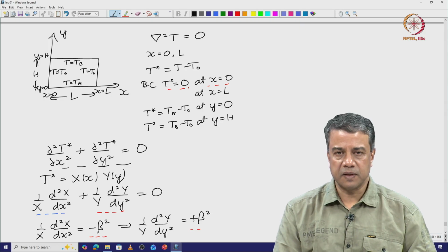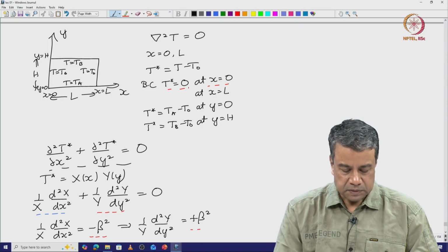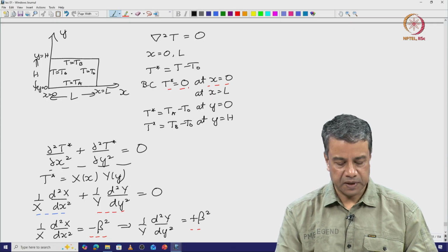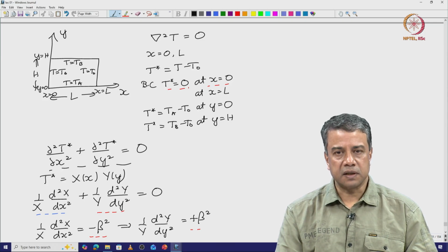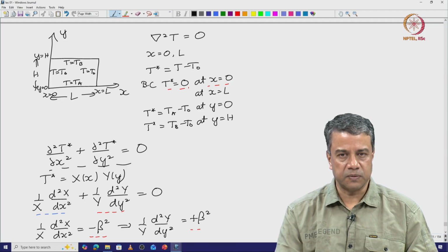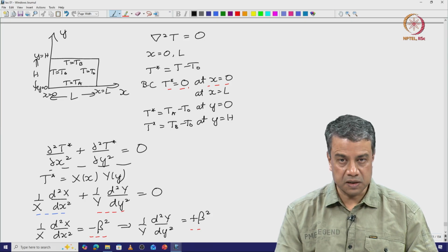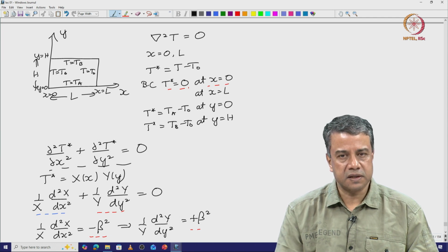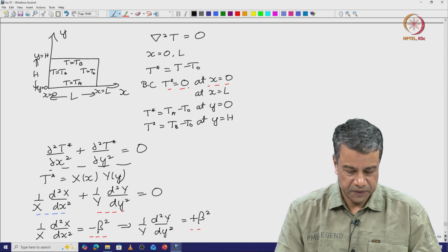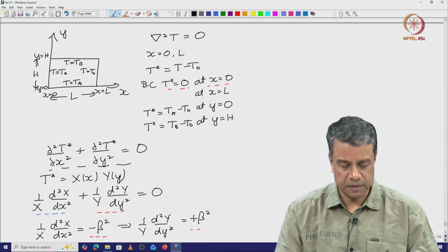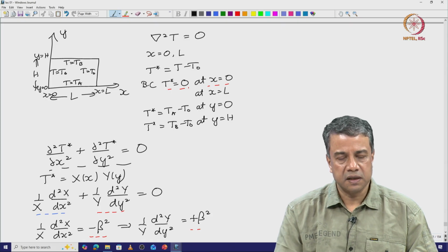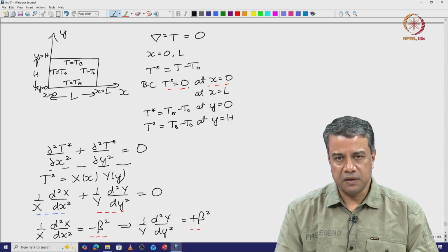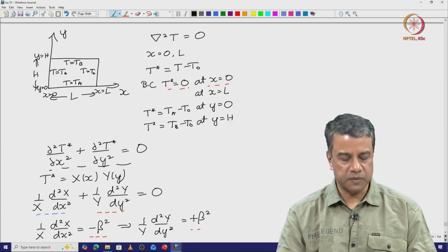When solving by separation of variables, if you recall, when we solved the unsteady separation of variables in one dimension, for the transient part of the temperature or the concentration field, the spatial boundary conditions have to be homogeneous. There is an inhomogeneous initial condition at initial time. Now, what we are solving for here is the steady state in 2 dimensions using separation of variables, and it is essential that the temperature field in any one of those dimensions be reduced to homogeneous boundary conditions.